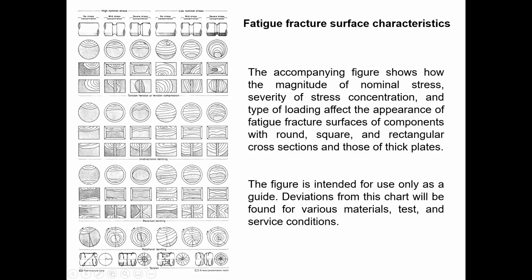So you can see the contour lines. Normally, the crack initiation point acts as the center point of the contour. So here this is a crack initiation, and in here there's another one. There are 2 crack initiations. That's how you can identify them. This is very important. You should have an idea, even if you are going to industry or a manufacturing company, as a mechanical engineer or material engineer, as an engineer, you should have an idea.